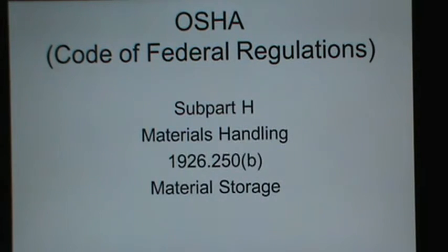You know, these are the types of individual pieces of information that you may be responsible for one particular day of your life. Let's go to subpart H, where we're discussing materials handling and storage, use, and disposal. We're going to highlight first of all in paragraph 250B, material storage. Materials stored inside buildings under construction shall not be placed within 6 feet of any hoistway or inside a floor opening, or within 10 feet of an exterior wall which does not extend above the top of the materials stored.